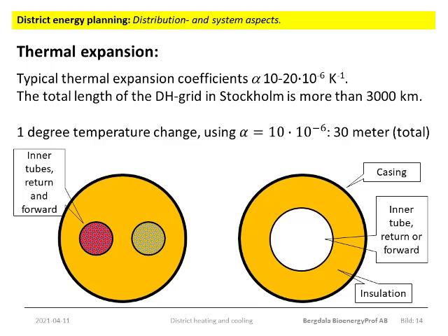Now the temperature is not constant in a district heating network, and the piping will become very long. Even small changes in temperature will finally have quite big consequences. Elongations and contractions must be allowed to take place in a controlled manner. Modern prefabricated district heating tubes will, whether twin tubes or single tubes, most often have margins built into them. There may, for example, be thin air slots around the inner tube or an elasticity in the insulation so that the inner tube may move a little from side to side.